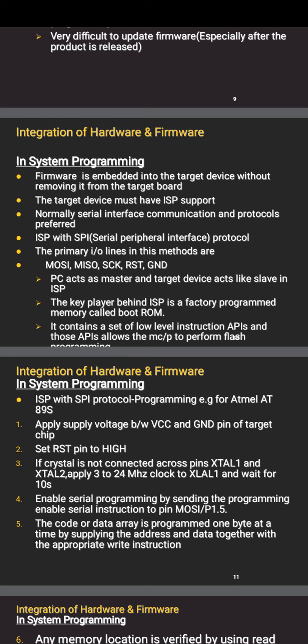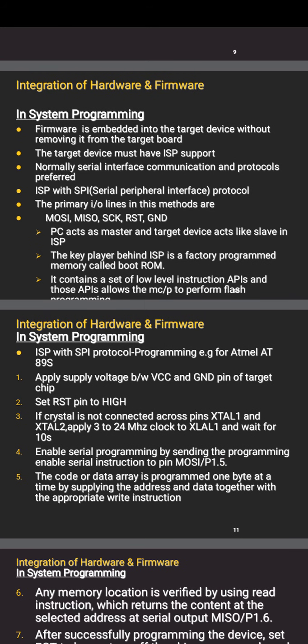And next are the steps. First we need to connect the VCC and ground to the target board and set the reset pin to high. XTAL1 and XTAL2 are crystal oscillators. This step is not at all needed.